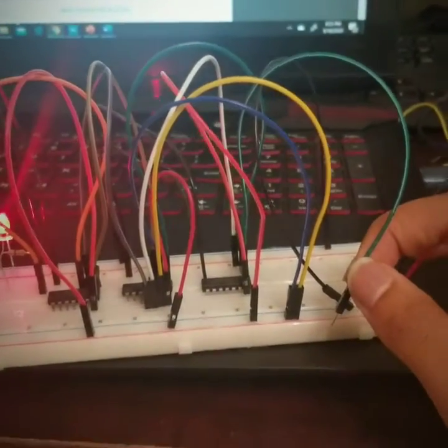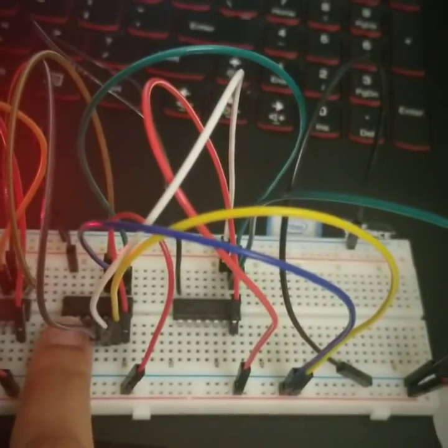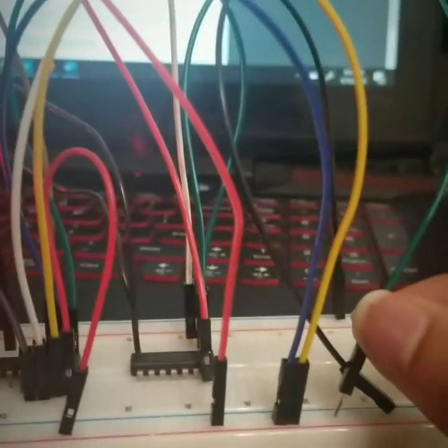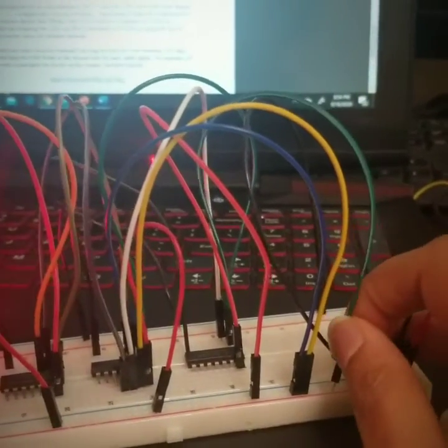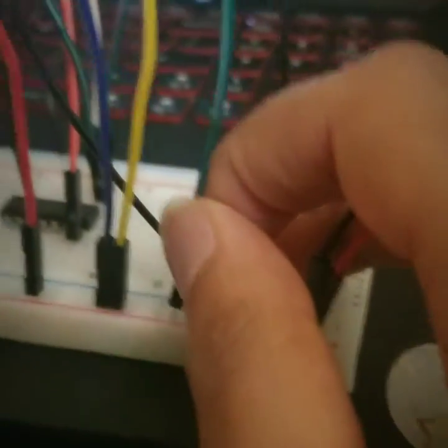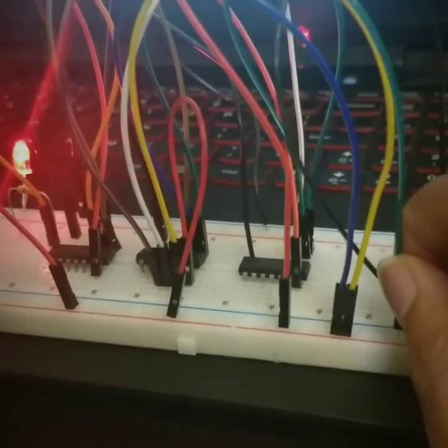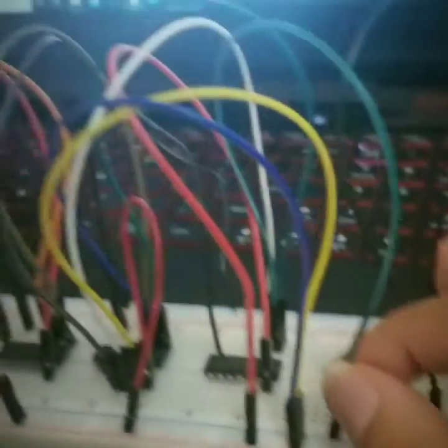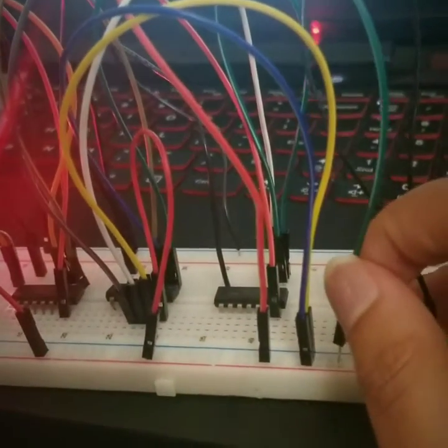As you can see, I've made the circuit in real life. This is the NOT gate, this is the AND gate, which is being used at both sides for both AND gates in the circuit, and then this is the OR gate. And as you can see, these 3 are the inputs, with the green being the selector. If I input this here and move it around while the other 2 are on, there is no change to my circuit. If we make it so that one of them is on and one of them is off, you can see that this does actually have an effect when the selector changes spots.